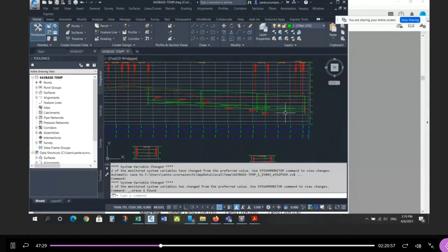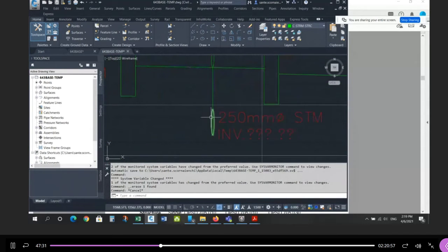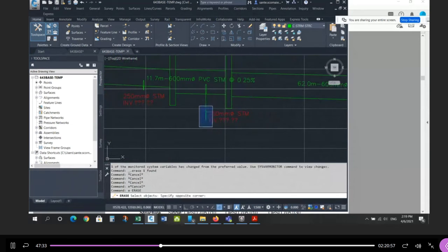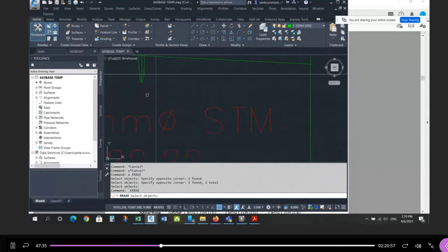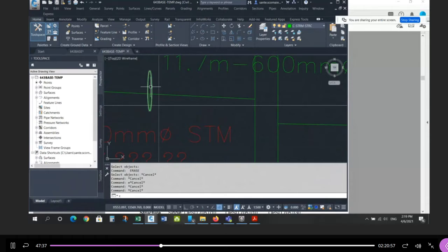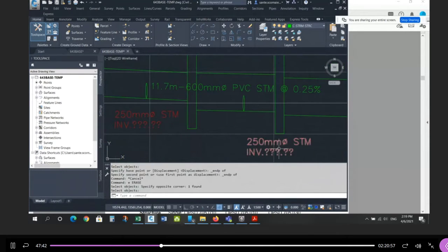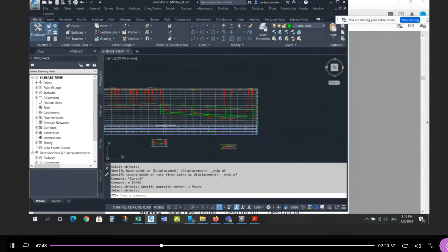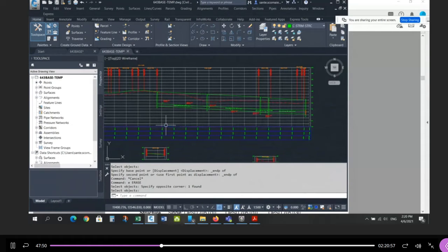Okay, so then in the profile, you'll eventually see this. Instead of this pipe down here, right, it'll be up here. And instead of this pipe down here, it'll be here. And you have to recalculate the inverts at the back of the lot where the catch basin is. And that's the final solution and the concept. Again, the numbers, the inverts are going to vary. They're going to be different for every student depending on how you drew your pipes. Okay? Any questions about that technique?